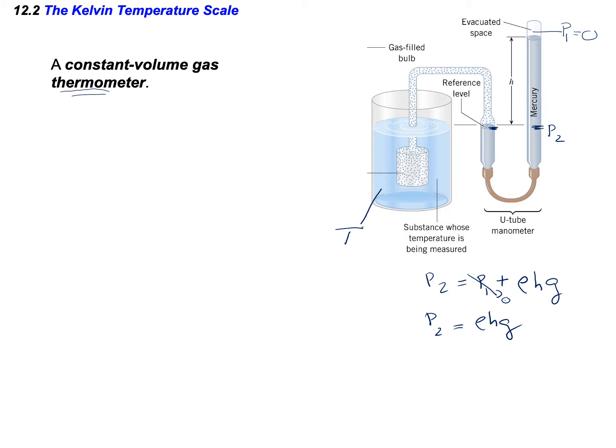So how do we measure the temperature? I can write an equation. The temperature T is equal to, let me write the equation first, and then we can go over the parameters, P1 minus P0 over P100 minus P0. P0 is the pressure at the ice point.